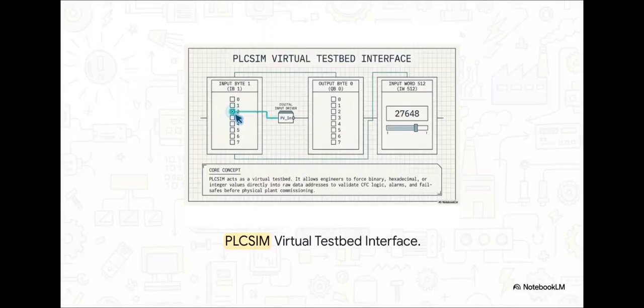And this is where engineers bring in tools like PLC-SIM as a virtual testbed. Through this interface, they can manually force binary states or punch specific hex values directly into the raw data addresses. What does that give us? It allows engineering teams to rigorously validate complex CFC logic, trigger alarms, and test all those failsafes in a totally safe, risk-free digital environment long before anyone even thinks about actual physical plant commissioning.